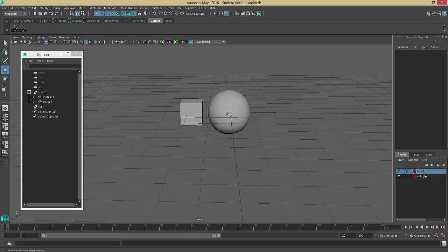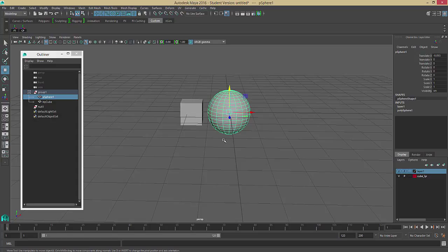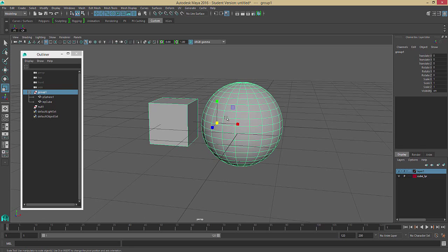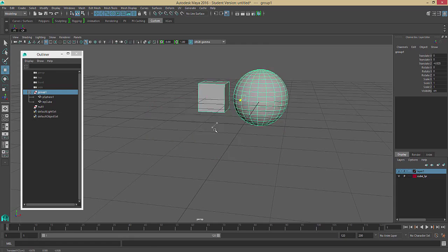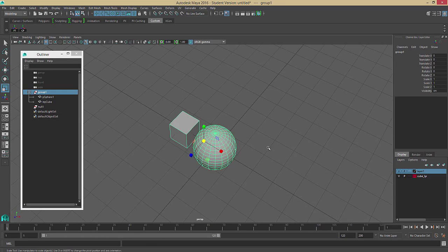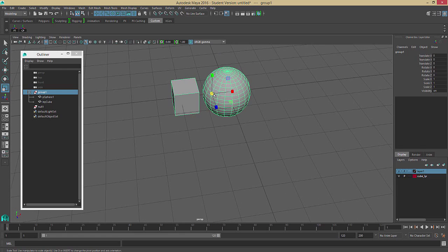A different way is, if you know that you have objects in a group, you could select one of the objects in the group and hit your up arrow key so that you go up, or down with the down arrow, to your group. So you're jumping up the hierarchy, like so. This is just another way to make sure that everything in your group can be moved, rotated, positioned, and scaled together, and scaled proportionally or from a particular point.